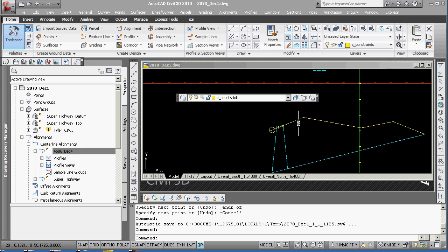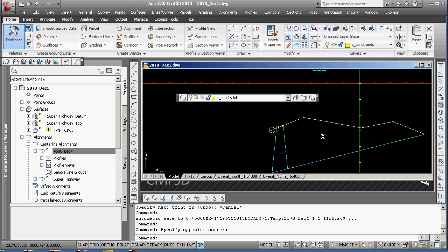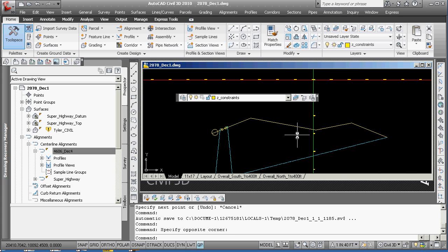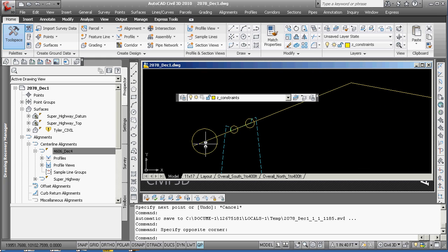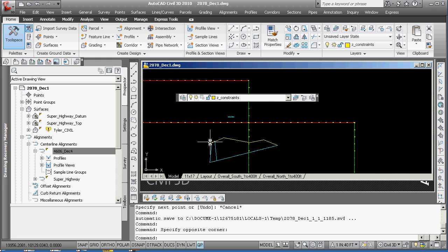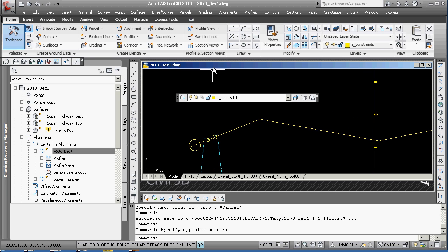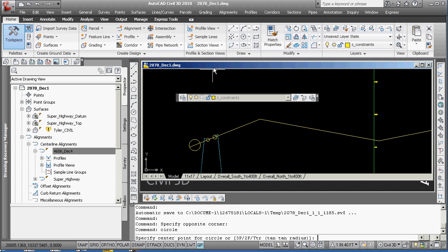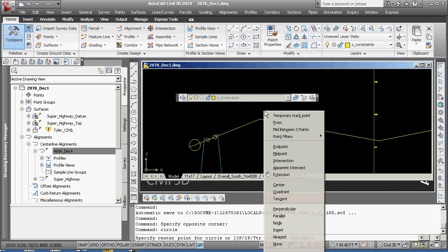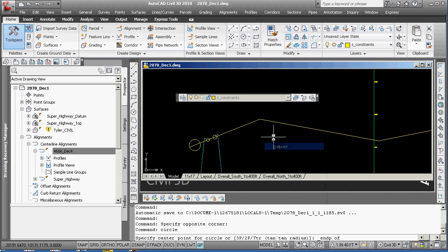Alright, I will point out now, though it looks like you have a profile in this drawing, you do not. You just have some data that is on a set of layers that you can transfer out. The problem is some people have a hard time managing it, so it's not a bad idea sometimes to go ahead and put circles at all of your key points, and then potentially when you need to, you can get rid of your line.